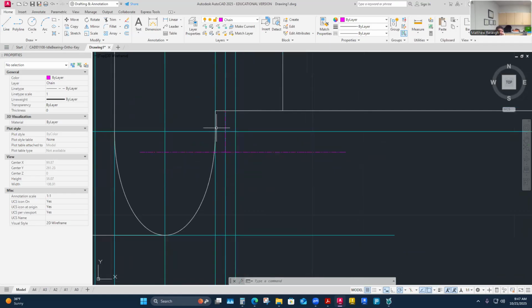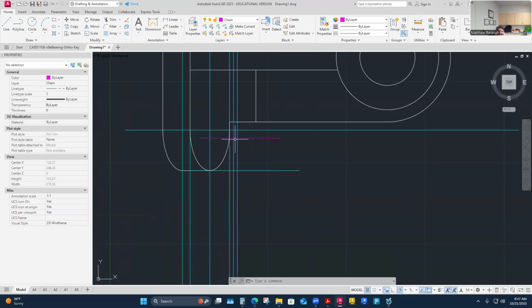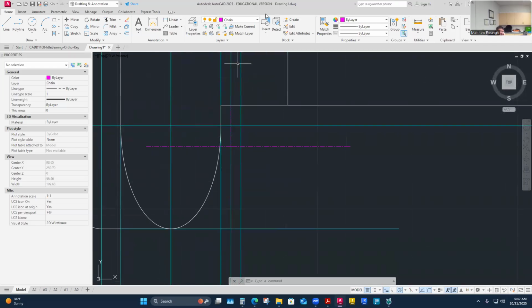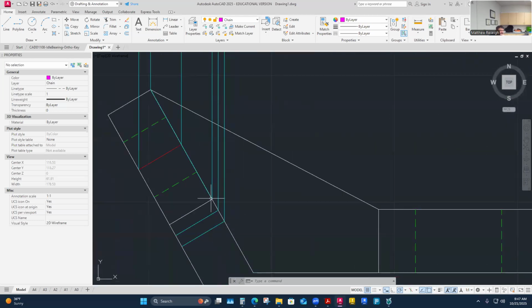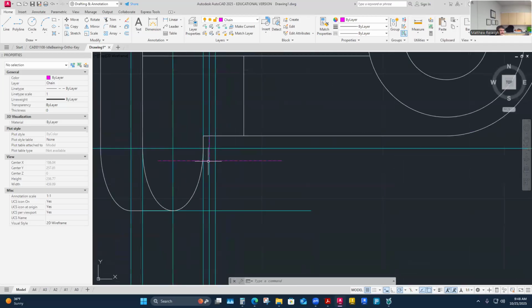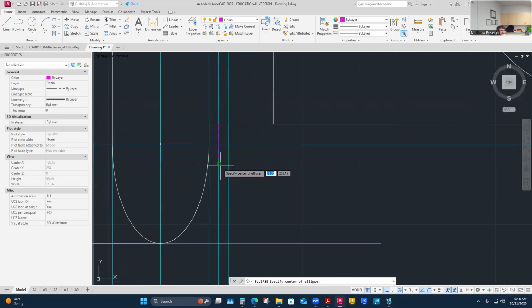and how it transitions back into the 80 millimeter wide here. So this, I'm going to use another ellipse here. And I think I've dialed in what I need. It's a 10 radius. And this is a 10 radius, but it's severely foreshortened in this view, right? This is what 10 radius looks like severely foreshortened in my top view. So that's the minor and the major axis kind of here of this. So I'm going to choose my center driven ellipse. Here's the center.